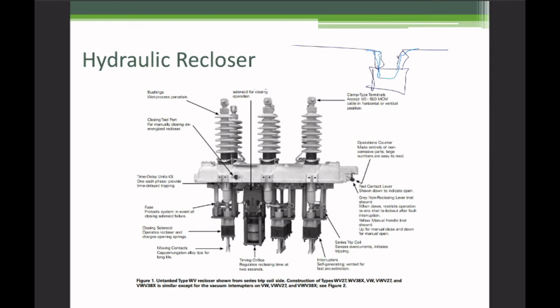And these rely on springs and electromagnets, and they pump oil around internally. And when the fault current comes, the electromagnetic pulse overcomes the spring tension, and it causes a cylinder to move. And if the cylinder moves, it displaces enough oil and causes a pressure rise, and it causes the switch to trip open. So they're a marvelous piece of mechanical engineering.